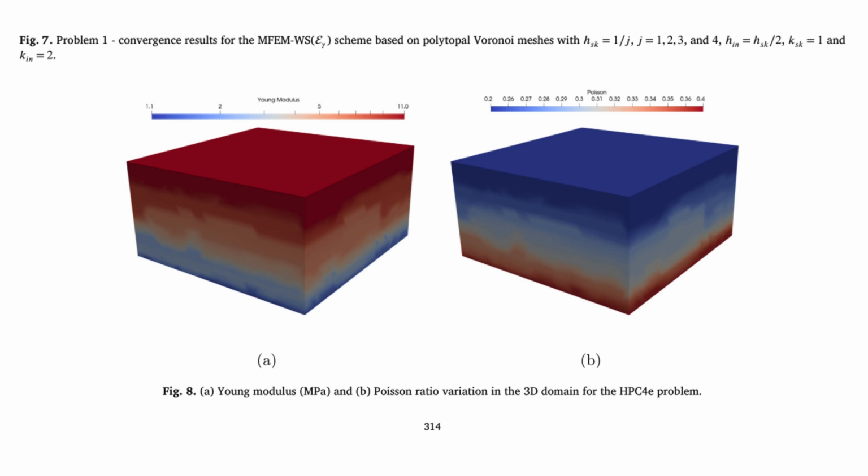They introduced a third variable into the mix, rotation, which they called rho. Wait, hold on. We want things simpler, but they added another variable. How does that help? It seems backwards, I know. But this rotation variable, rho, acts as what's called a Lagrange multiplier. Its whole job is to weakly enforce that symmetry constraint.